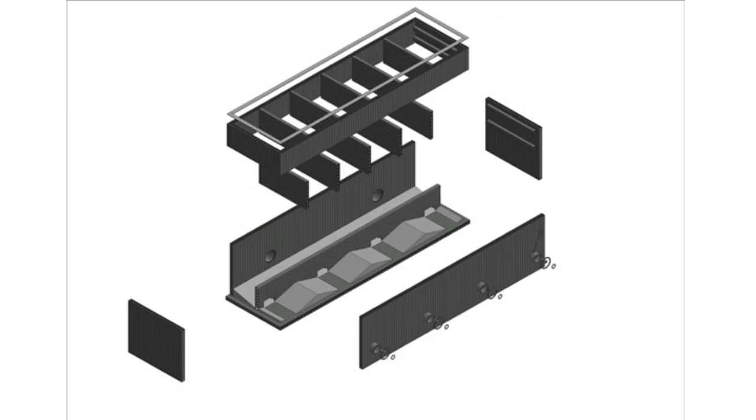Another exploded isometric view, again to show our capabilities. This is stormwater, and in this particular design we've put baffles into it, which allows a more rapid settling rate of particles, so we have cleaner effluent coming through.